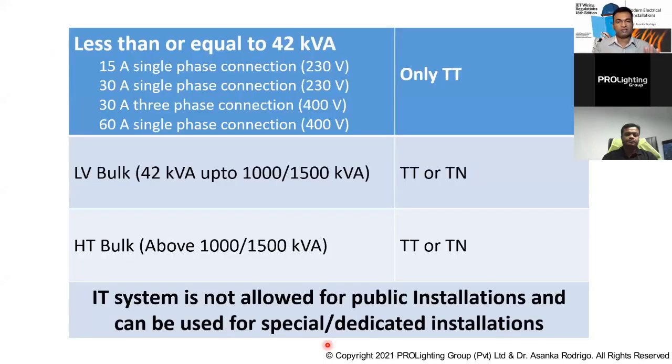That is the only restriction, because when you look at our distribution system, the normal distribution transformers, you may have seen that they are running with only 4 conductors, that is 3 lives and the neutral. And the normal practice in the distribution system in Sri Lanka is that we are not continuing the earth connection, and that is mainly to reduce the cost, not for any other reason.